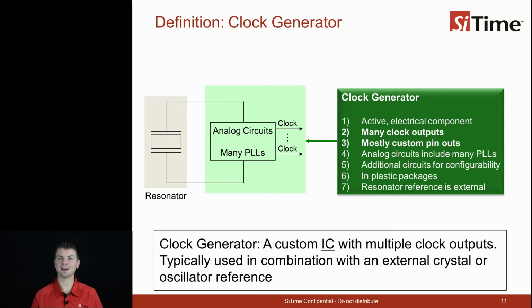Clock routing is more complicated due to sometimes long traces from the clock output to each IC. Long clock traces can result in worse EMI due to longer ground loops. The EMI challenge can be improved by the use of spread spectrum clocking.